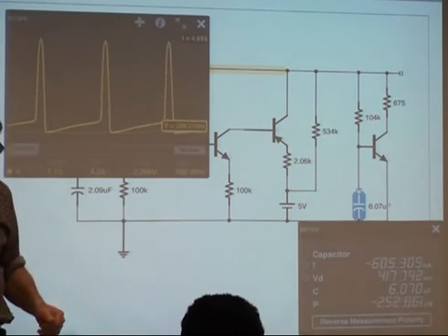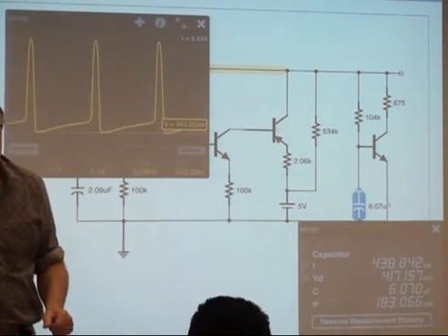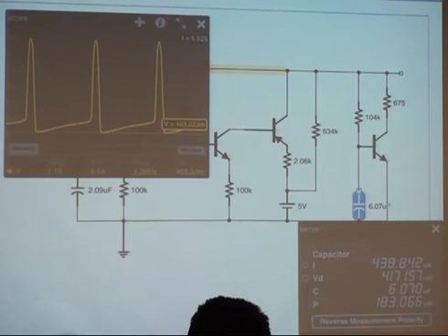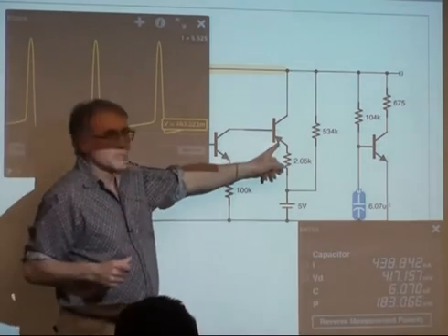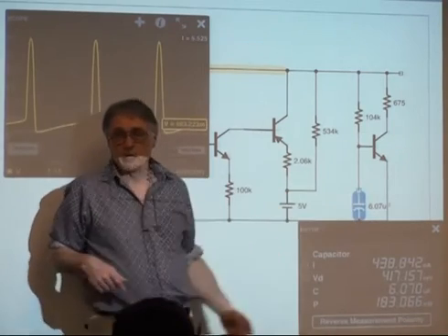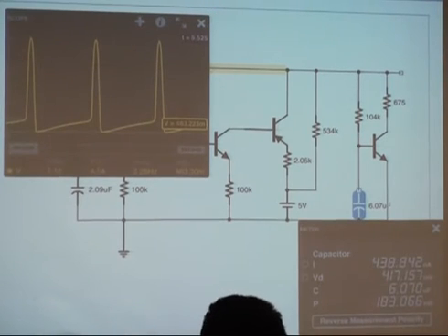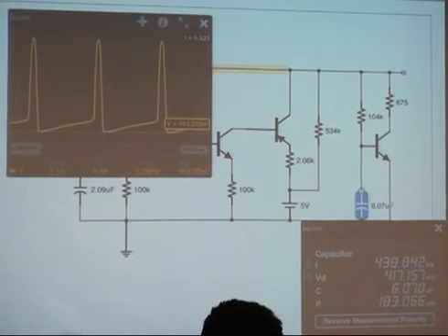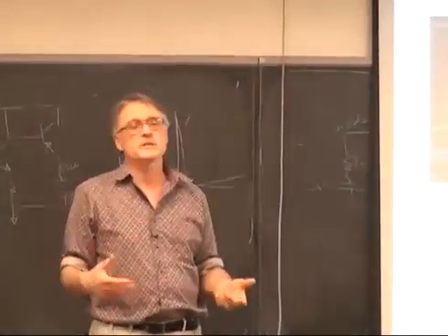So the values that you had initially were standardized values from the research? The values I had were ones that oscillated. It turns out that SPICE doesn't do tremendously well on this kind of circuit for the following reason. There are some extremely fast processes because of the positive feedback here, and some very slow processes. That says to get good accuracy, you have to take a lot of little tiny steps. And so the system is ill-posed, or ill-conditioned. Or in the vernacular, it's a stiff system.